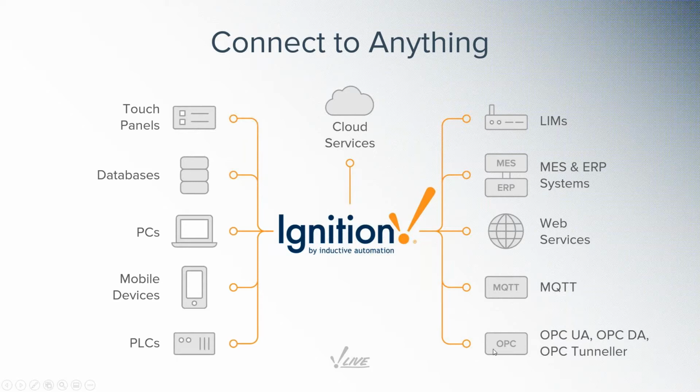We also can support connecting to third-party OPC servers, whether that could be Kepware or Matrikon, or even devices that support OPC UA built in. It allows us to really get access to all of your industrial data, bring it into Ignition. We can work with any SQL database. That could be MySQL, Microsoft SQL Server, Oracle, Postgres, and more. We can interface with MQTT to either publish data or subscribe to data, or even be a broker.